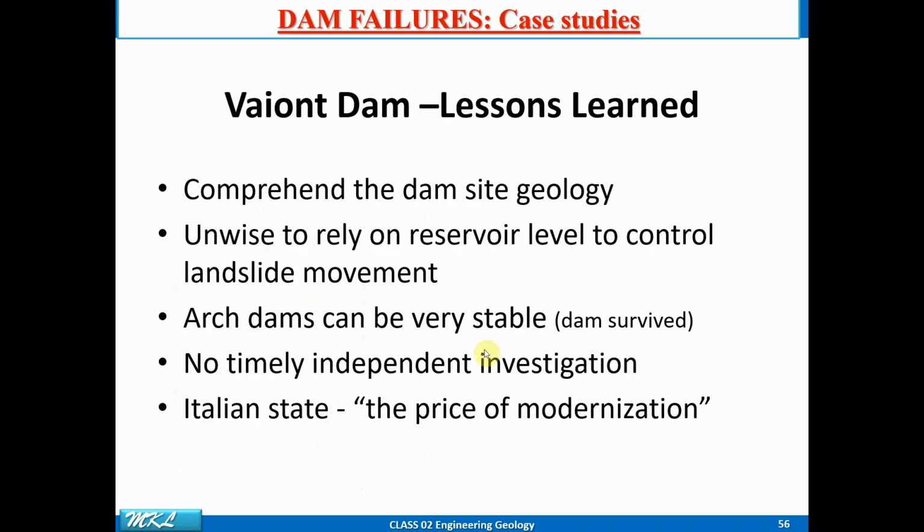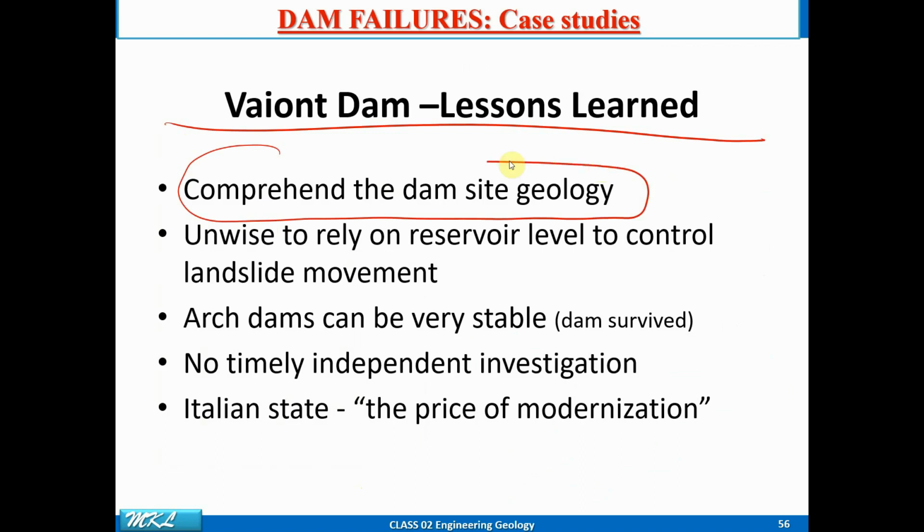So the lesson you should learn from this dam failure is that you have to understand the dam site geology. Don't just trust the engineering geologist; you also have to understand the report they submit, which is why this course is in your syllabus. And it is unwise to rely on the reservoir level to control landslide movement.